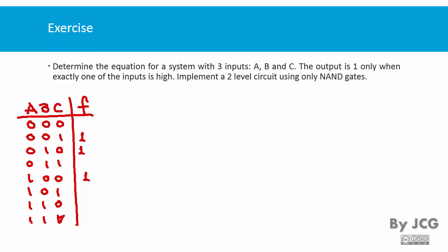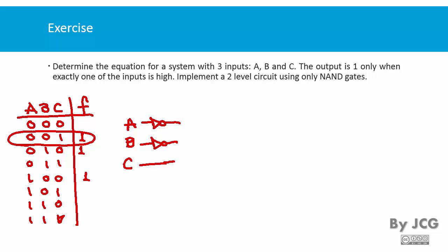So we already know that this type of problem doesn't have a minimization. So we're only going to focus on the first one, on this one here. What kind of circuit can we make to detect this code? Well, it's a minterm. So we need to do something like this. That part would give me a 1 for that specific combination. So when you are asked to do this, what you have to do is make the adjustments to get that same function but using only NANDs.